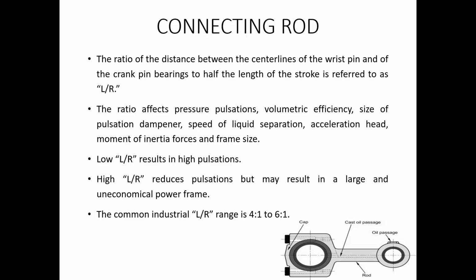Now usually in connecting rods, we may have certain passages for the flow of engine oil or the cooling oil. So we have the oil reservoir or the oil pump at the bottom, where the oil is pumped sometimes through the holes that are drilled in the connecting rod.